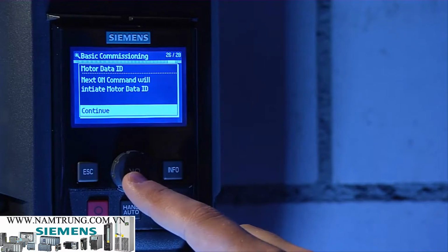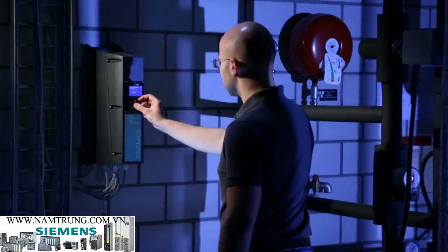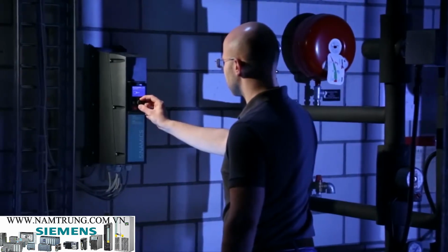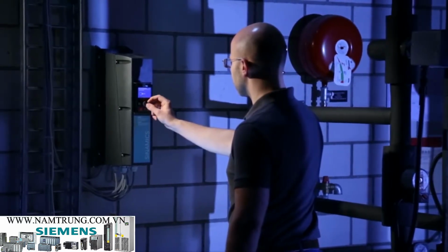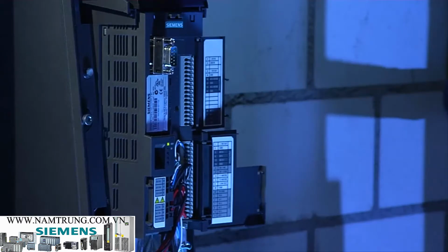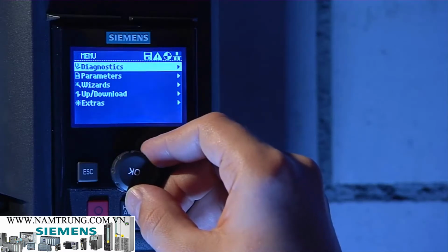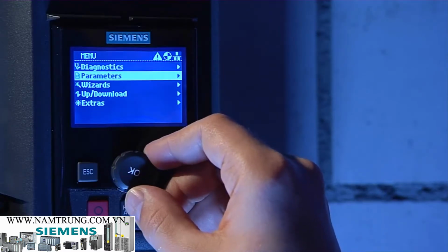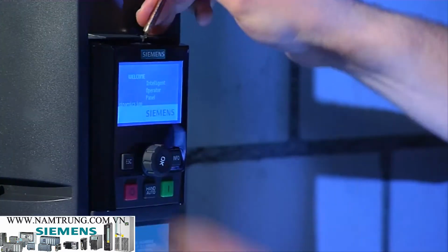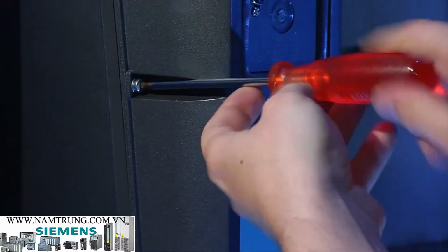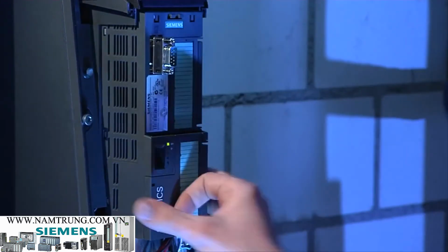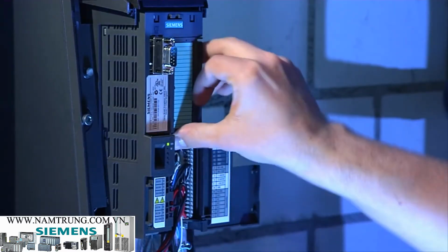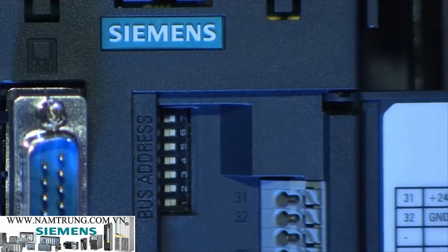The only thing that needs to be done now is to change the field bus address to the required value. There are 2 ways to set the Modbus address, either using the dip switches on your control unit or by parameter. We will show you how to set the Modbus address by parameter. First, make sure that all dip switches for the field bus address are in the off position. The Modbus address will be controlled by the control unit only if all dip switches are in the same position.